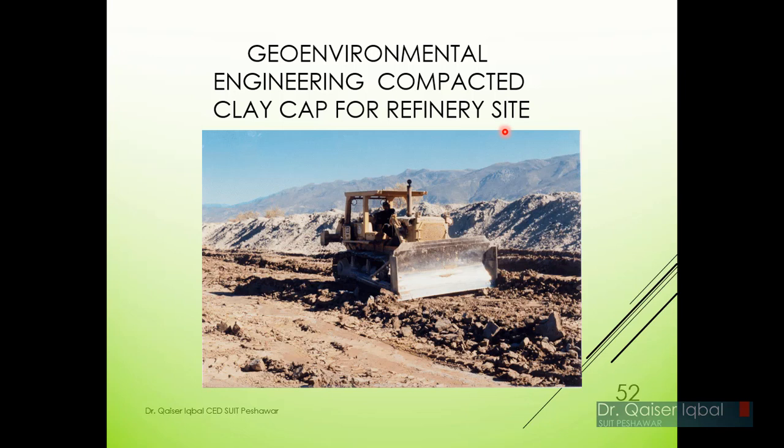So their foundation design not only includes a safe foundation and design in terms of the loading, but in terms of chemical entering the ground as well, because there will be a lot of chemicals being leaked in the refinery, being disposed of in the refinery. So if they are going through the floor, they will go into the groundwater, okay. So what we do is we provide a clay cap, okay.